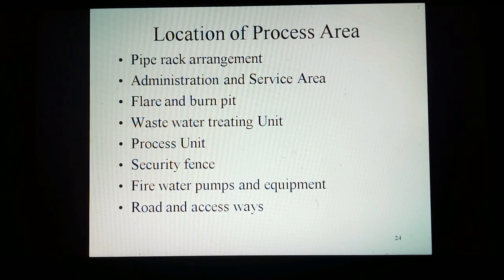The minimum space between security fence and units boundary shall be 20 meters, and between security fence and equipment shall be 30 meters. In case of special units such as flammable material storage with vapor release and toxic materials, minimum space shall be at least 60 meters from site boundaries adjacent to centers of population, domestic, work or leisure.